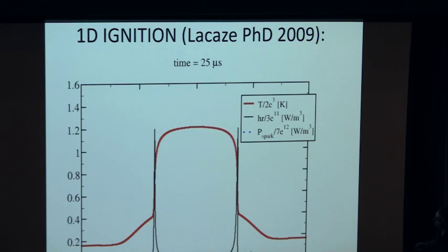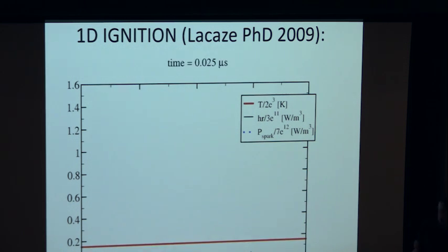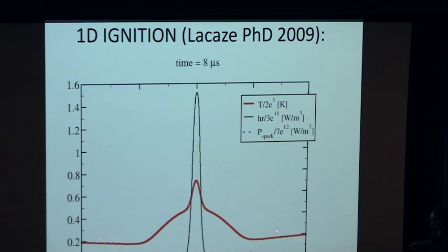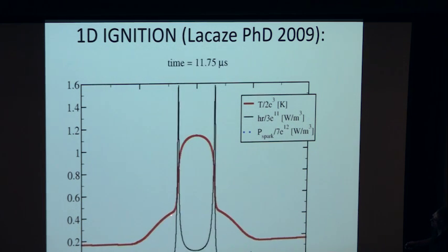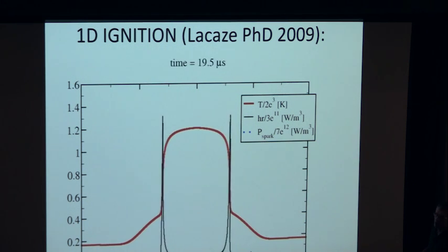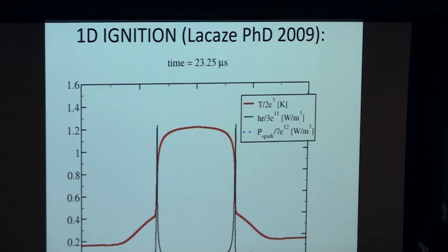Okay? Again, to come back to the discussion we had a long time ago, look at the scales here. We're talking about flame fronts, which are, this is meters, this is millimeter, this is a few fraction of a millimeter. There's no way you can capture that if you don't have the mesh to do it. So same thing again, you deposit energy, and then you stop. Temperature has gone up enough. Then chemical reactions begin. You have here the two shock waves going away. They're not shocks, actually, they're acoustic waves. And then finally you ignite. Okay? So even without the plasma phase, it's a complicated story.